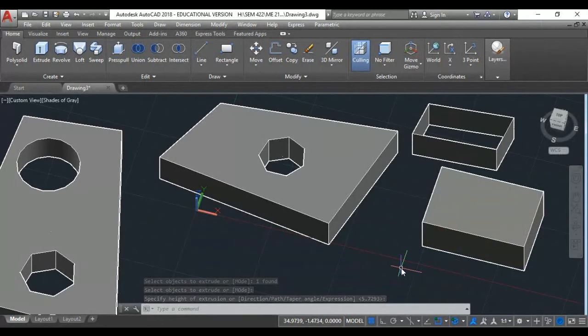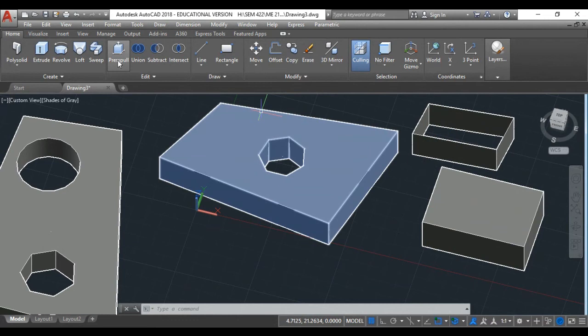If you are drawing your object as one click, one command, this means that you are able to make it a solid. But if you are drawing an object with a combination of these separate lines, this means that you will not be able to draw the object as a solid model. Clear? You got the difference, guys? Okay, I will take you back to the same two rectangles, but this time I'm gonna use press pull.